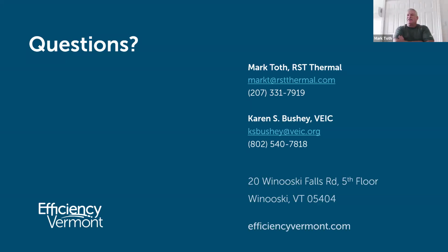Yeah. Right. The easiest one to use and the cheapest monitor to get is the CO2 monitor. So you can use that. I don't know what your position is, but if you're with a homeowner and they're talking about putting in a ventilation system and you meet them in their home and you go in their kitchen, maybe sit at the kitchen table, and if you just turn on that CO2 detector while you're there, you're going to see it going up and up just from the 3 or 4 of you talking to each other.